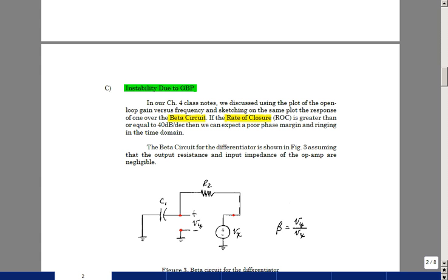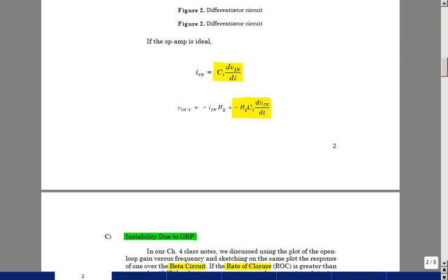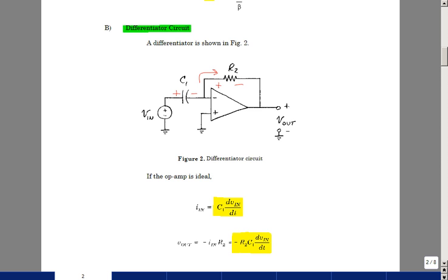Now, our technique in class was to turn the algebraic expression into an equivalent circuit so that we could think about manipulating the circuit for improving stability. If we go back and look at this schematic, the technique we talked about with beta networks was to erase these things that are here, set this equal to 0, cut the op-amp out, and put an independent source here.